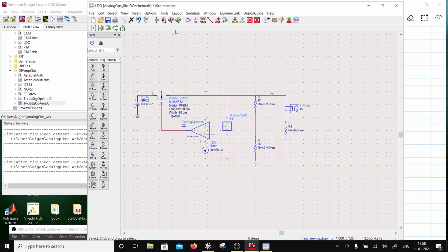Okay, so this is the simplest LDO I can make, and here you can also do overcurrent protection on this node and stuff like that, right? So you can put a circuitry for overcurrent protection, which will switch off this MOSFET when the current drawn increases to a limit. So I'm not going to go into details of LDO design. There are different things that can be added to this LDO, but this is the simplest LDO.